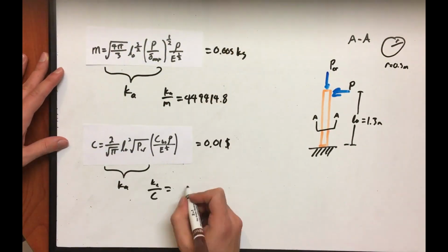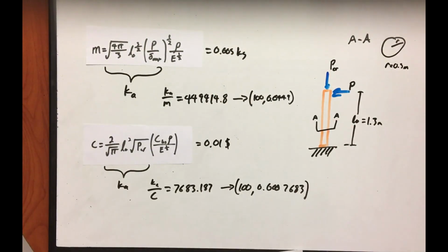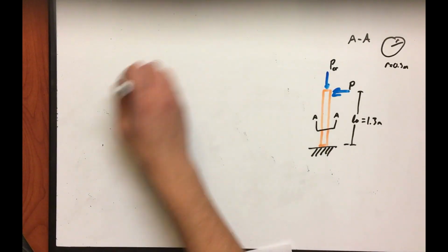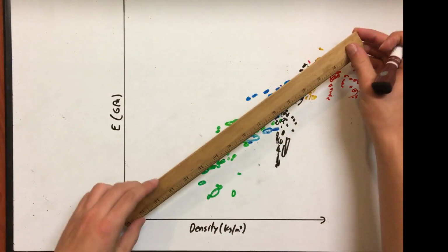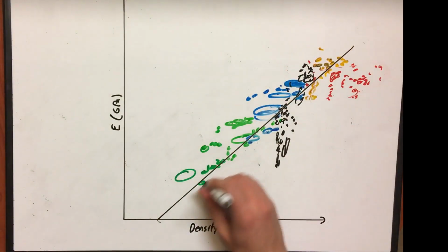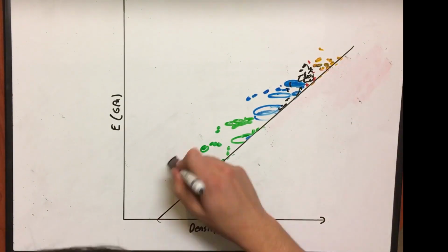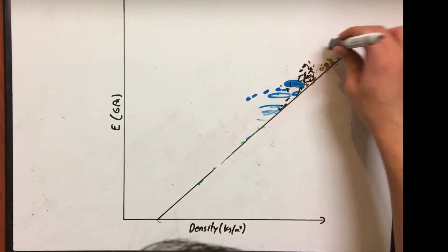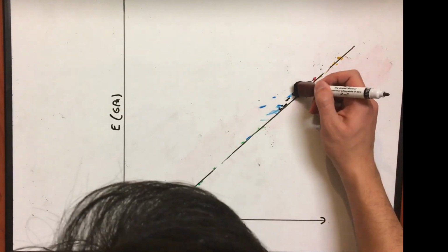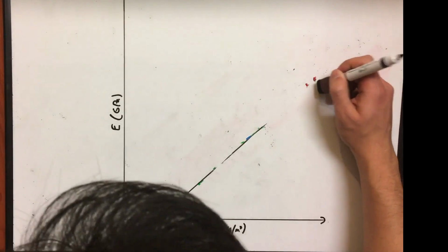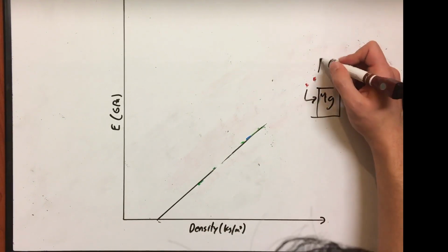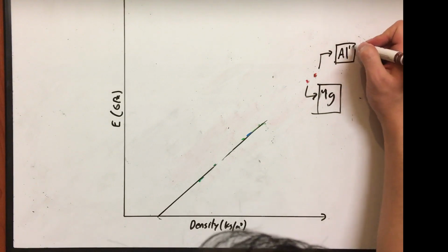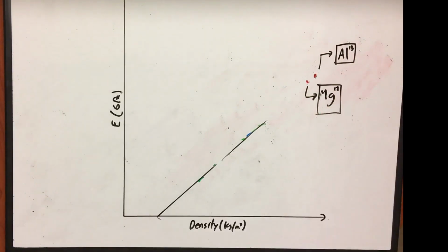From the assumptions and calculations made, we can find the values for constants in the MPI equations and calculate reference points for each graph. The selection lines can be drawn. After applying MPIs based on applications or manufacturing constraints, we selected materials that were recyclable, water resistant, UV radiation resistant, and could easily be machined and manufactured. This left us with magnesium and a wide variety of aluminum alloys.